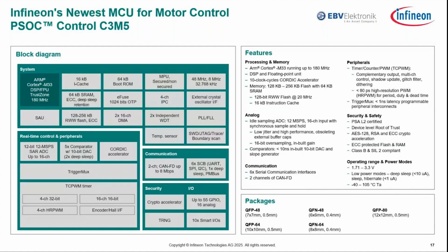I will also cover another critical topic shortly, which is timers for motor control, and the trigger mux system, which enables effective coordination between the ADC and the timer blocks. Interactions between peripherals can happen in less than 1 nanosecond, allowing the system to operate automatically without needing CPU power.